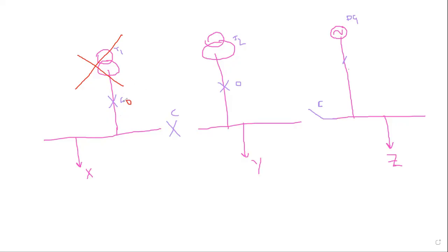Yeah. This has to be opened up, and this should be closed. Now, this transformer is feeding all the loads. And I have not seen, because it is in normal position, after failure of this one, I charged this, without testing anything. So this transformer has also failed.